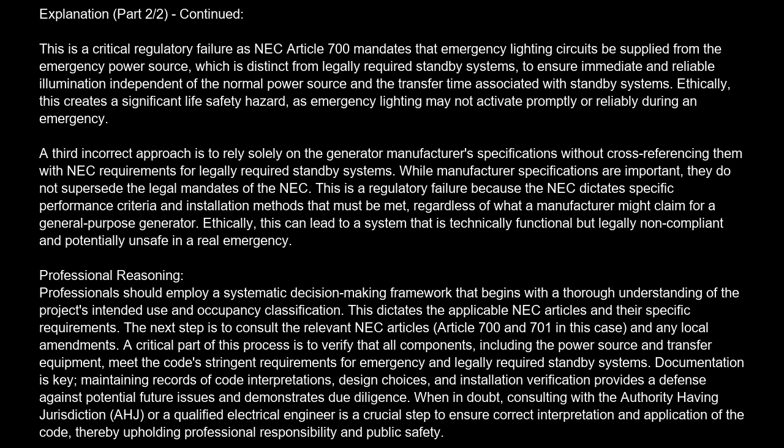Professional reasoning. Professionals should employ a systematic decision-making framework that begins with a thorough understanding of the project's intended use and occupancy classification. This dictates the applicable NEC articles and their specific requirements. The next step is to consult the relevant NEC articles, Article 700 and 701 in this case, and any local amendments.